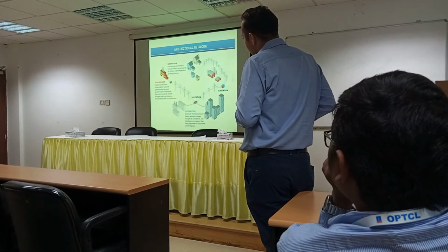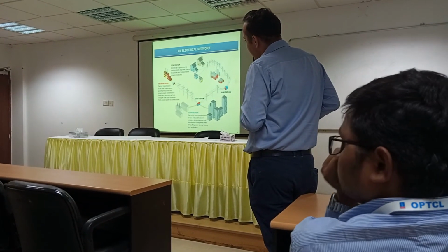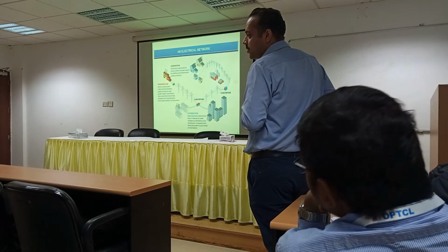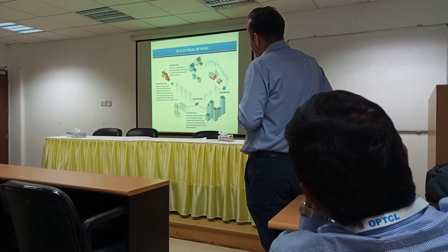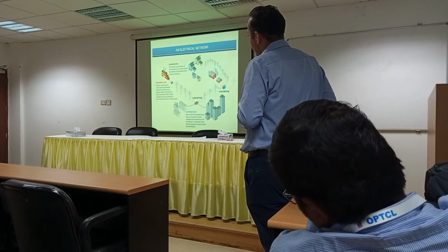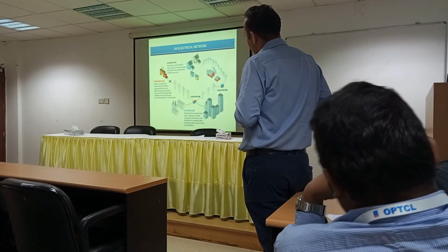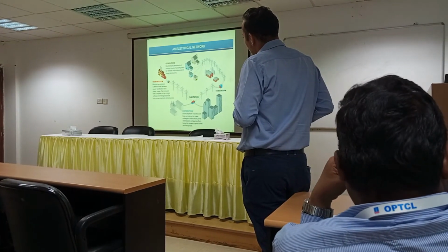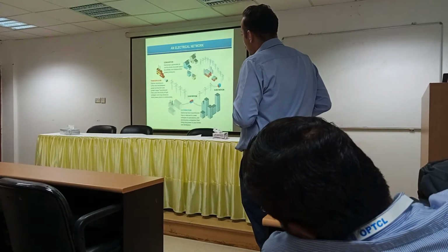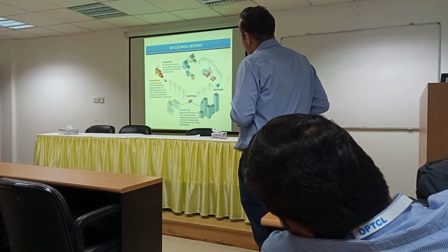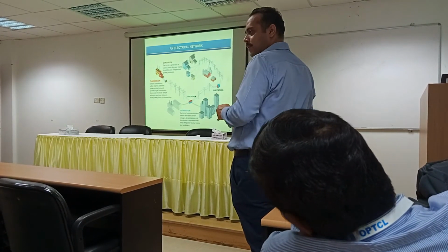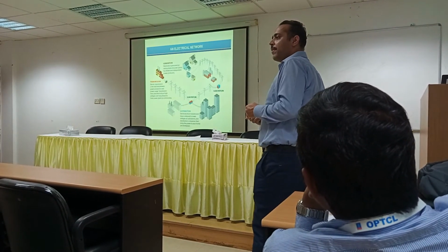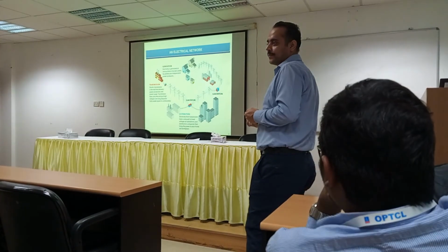They set up a small industry substation where they will have 33 kV and 11 kV and arrange the utility. With this substation we have 220 to 33 kV, with a line in and a line out, because 220 kV comes in and 220 kV goes out to another substation. So in a particular region we also step down depending on the utility requirement, right?